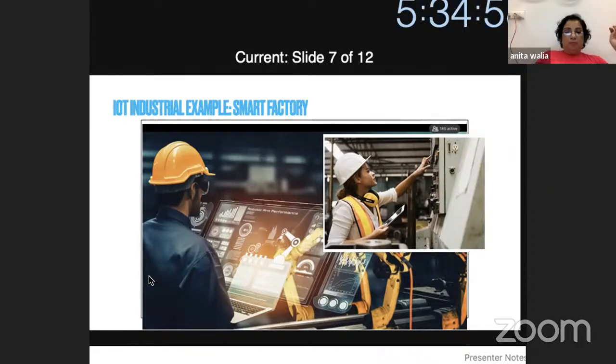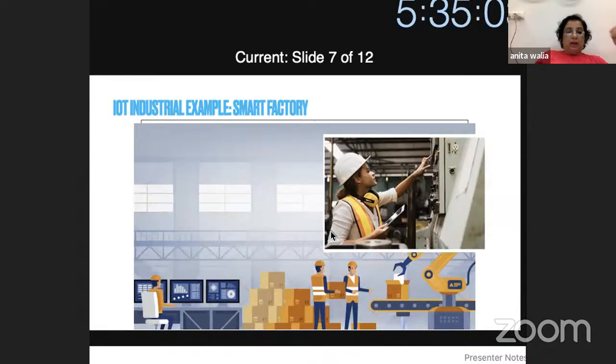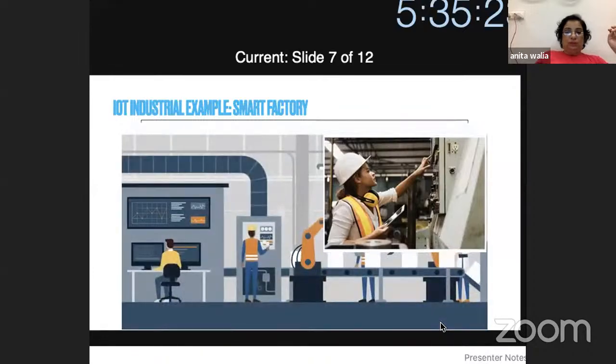So the monitoring is used within the field, or it is remote monitoring which can happen using wireless or wired communication. The data generated from the sensors are collected, transferred, and stored in the cloud. These data, stored in the cloud or data centers for monitoring and data analysis, help the company in sensing unusual situations. An example: if the temperature of a piece of equipment exceeds a certain specified standard, the sensor can detect this and send a signal to stop the breakdown before it occurs.